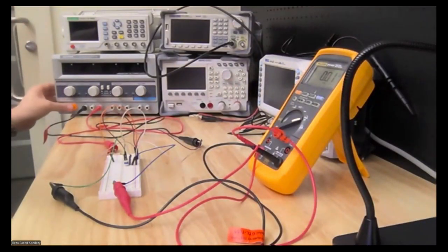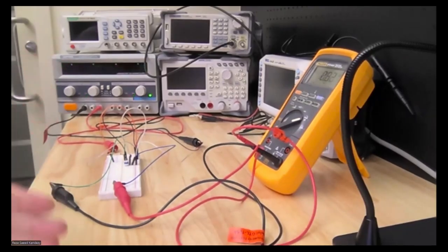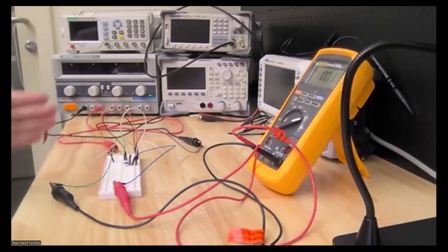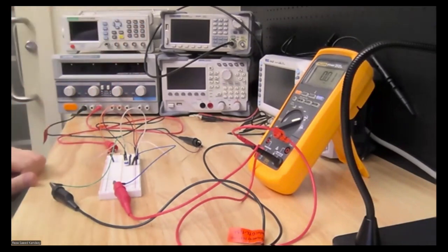Now we changed it. We are gonna apply the voltage. My multimeter reads 12.3 milliamps. Okay, so it's 12.3 milliamps. So based on that value and the 51 microamp current in the base, I can now calculate the beta for this specific BJT.